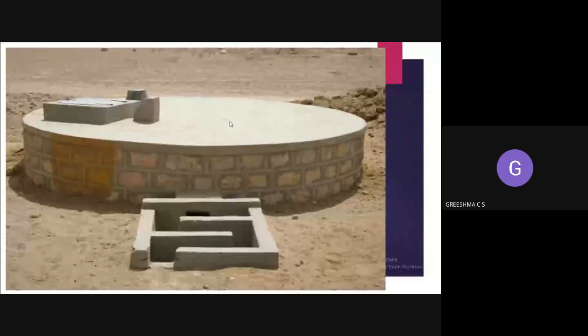Okay, so unlike a rectangular slab, the construction and reinforcement of a circular slab is entirely different. We have learned about the reinforcement details of a normal rectangular slab, whether it is rectangular or square, whatever it is. One-way slab and two-way slab, we have learned about the reinforcement. How are we providing reinforcement? We provide reinforcement on the bottom side, and then on the top side. That's what we provide for a normal rectangular slab. Coming to a circular slab, this is how we provide the reinforcement.